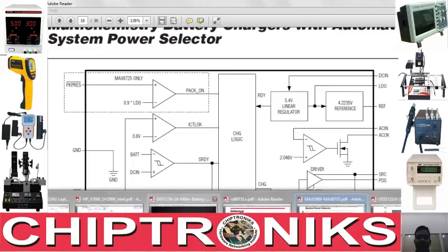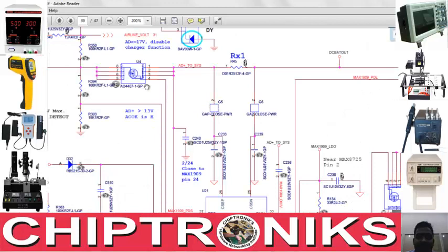In that case, what would happen? If this PDS, if gate becomes the value of SRC, that is adapter, then this VGS is equal to 0. So VGS equal to 0, that means this MOSFET will turn off. No current will flow across this. This DC bat out will not flow across this, because we know in a P channel MOSFET, when input is connected here, if adapter is not present, DC bat out is present, here it acts like an input. Input is at source. To flow the current from source to drain, VGS has to be negative. But here, in that case, the PDS is pulled to SRC.